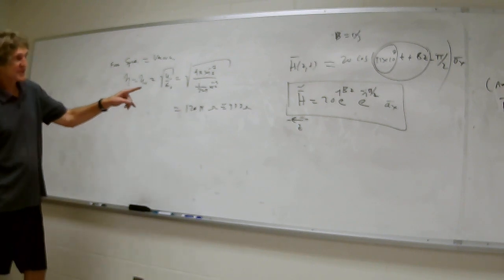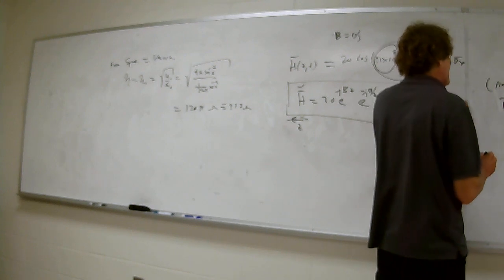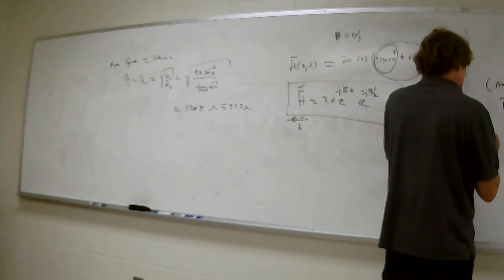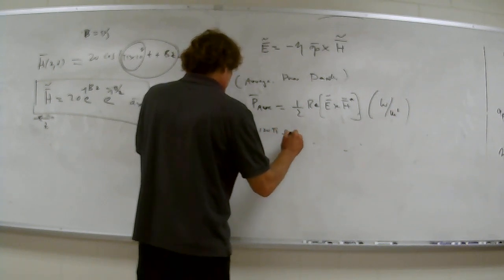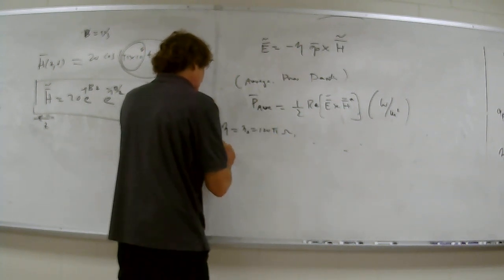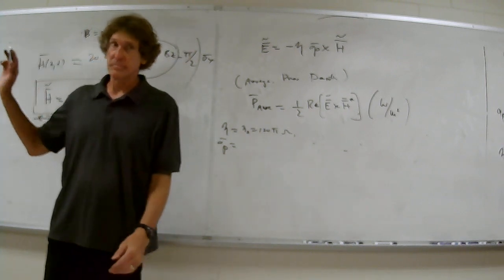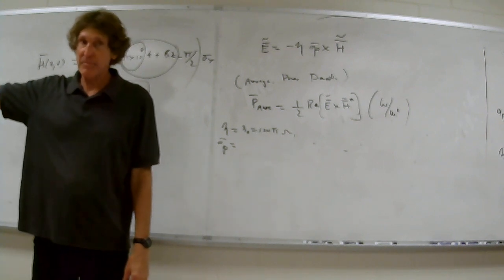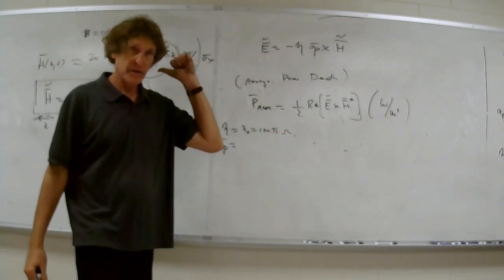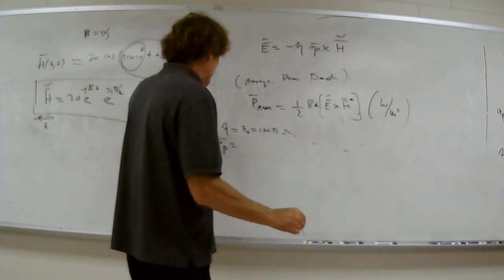All right, now let's do this. Let's go ahead and get the E field. So for our problem, eta is eta naught, equal to 120 pi ohms. What's the direction of propagation? A unit vector in the direction of propagation? It would be minus AZ. Remember, it's going in the negative direction because beta is positive. Y'all follow me in this class? So it's minus AZ.